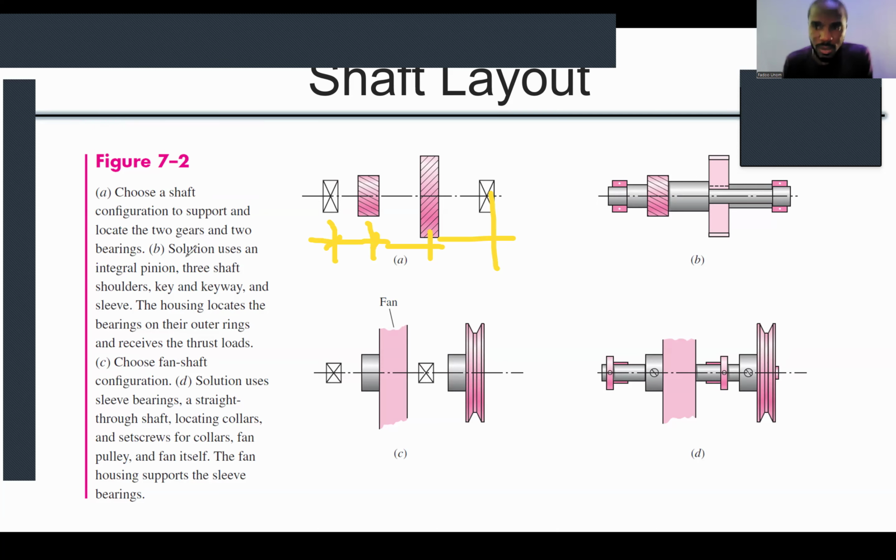All right. So when you locate these, then in the B part, you can begin to say, okay, how should my shaft be? Look here, I have stepped shafts. The first step stops at the shoulder where the bearing is supposed to be located.